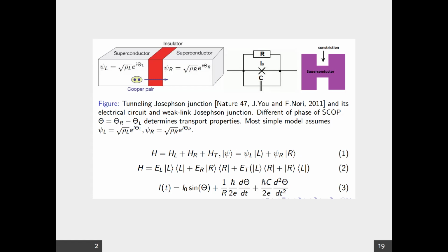is nothing else but this I_T. This current goes via two different channels: a non-dissipative channel and a dissipative channel. The dissipative channel is the presence of R. There is a Josephson, superfluid current flowing and a current of normal particles. So basically the three elements of the RCSJ model are reflected by equation 3.